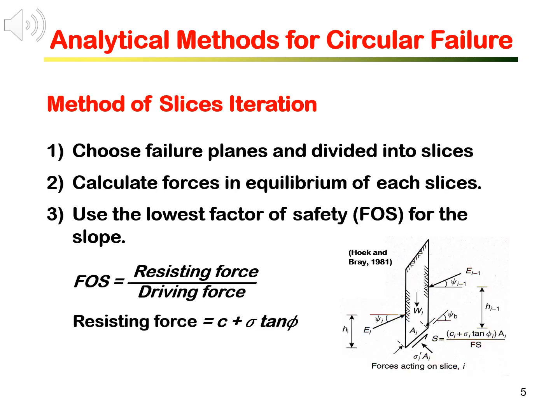The limit equilibrium method using the method of slices technique is an iterative method. It starts with choosing failure planes and cutting the sliding slope into slices. Then we formulate an equilibrium equation of forces acting on each slice, and the sliding driving force and the sliding resisting force along the sliding plane.